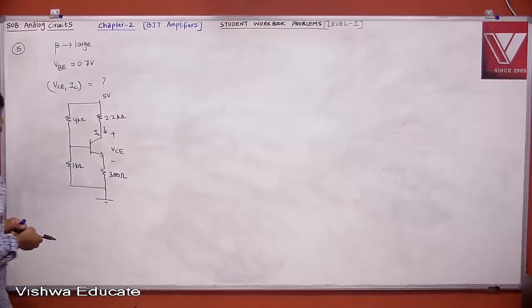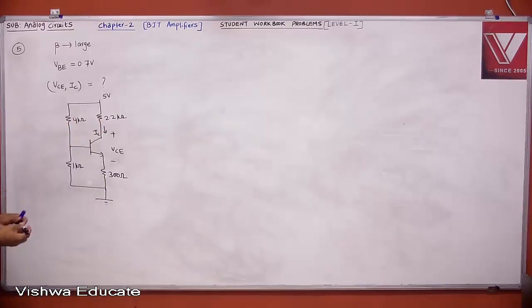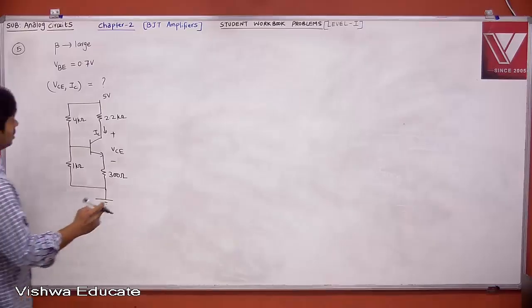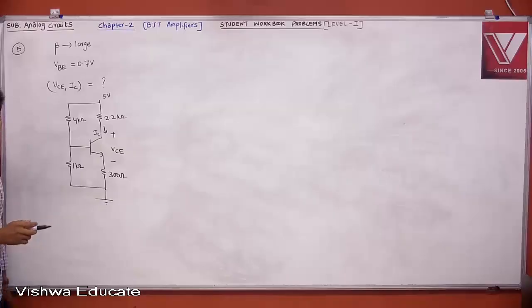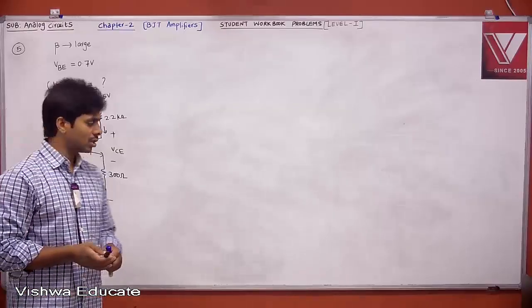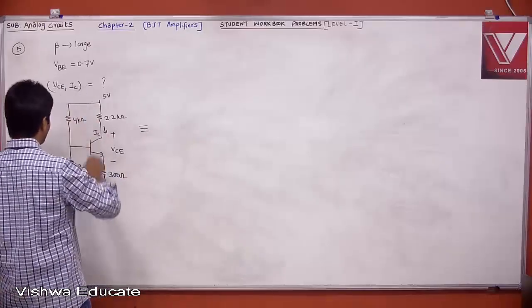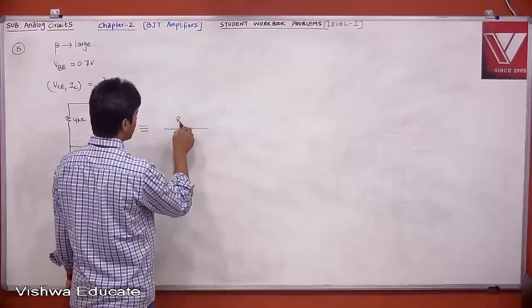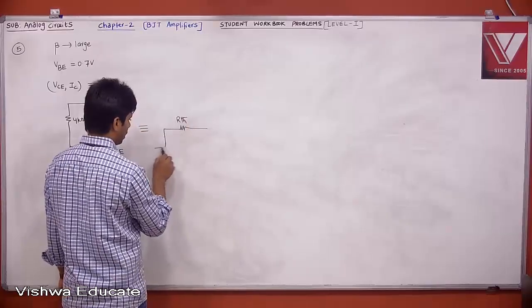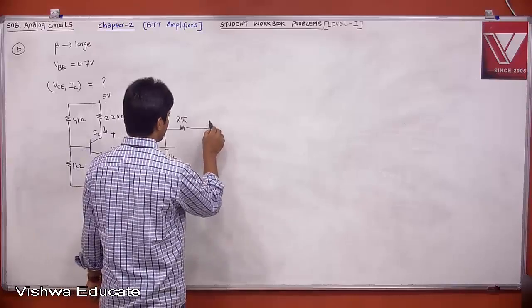Okay. Now tell me, what is the circuit which we had seen already in BJT DC analysis? This is nothing but a self bias circuit, right? Now what is our aim? Our aim is to calculate the operating point VCE comma IC. That we can find using KVL equations. Now can I equivalently apply Thevenin's theorem for this? Then you will get V Thevenin and R Thevenin. This is your R Thevenin, and this is your V Thevenin, and this is your circuit.